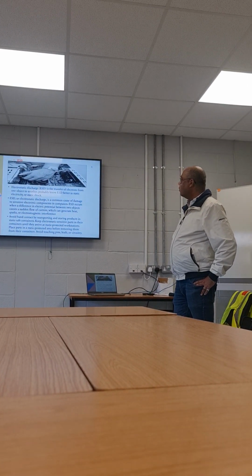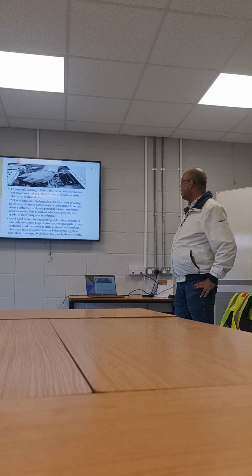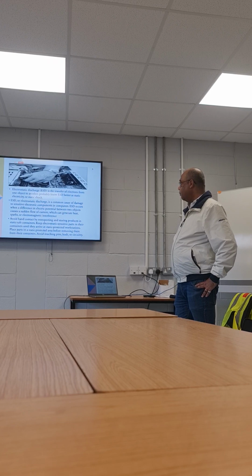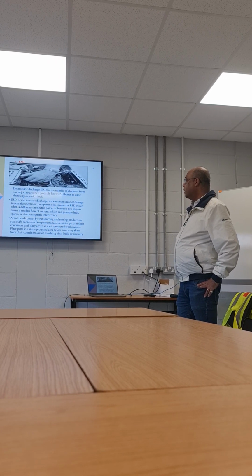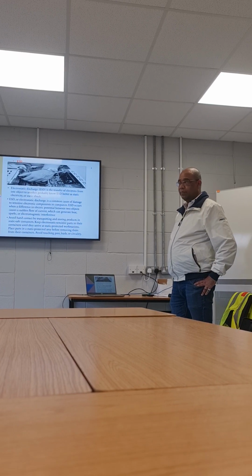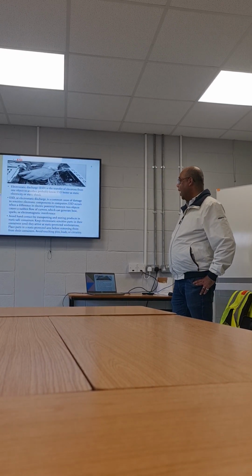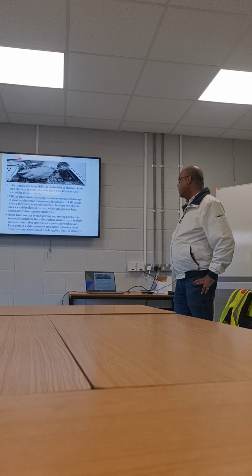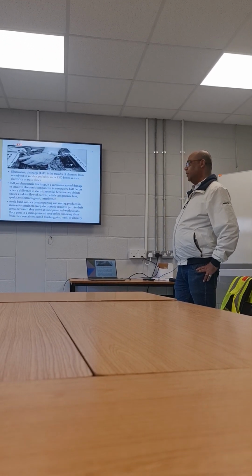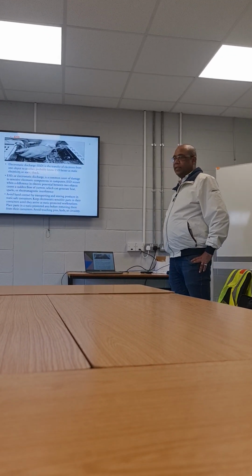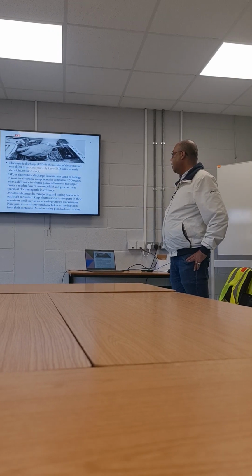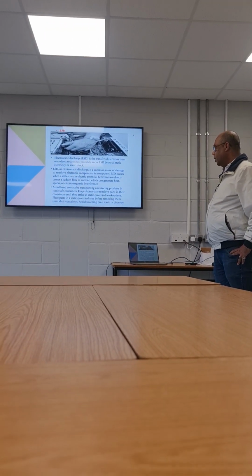ESD occurs when a difference in electric potential between two objects causes a sudden flow of current, which can generate heat, spark, or electromagnetic interference. So avoid hand contact by transporting and storing products in a static safe container. Until it's in a safe container, you shouldn't touch it, not even the pins or any of the components in the workstation.